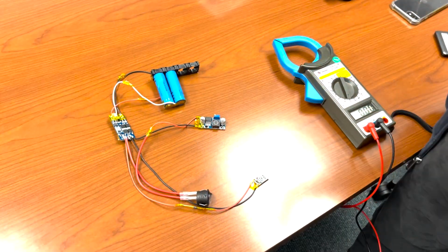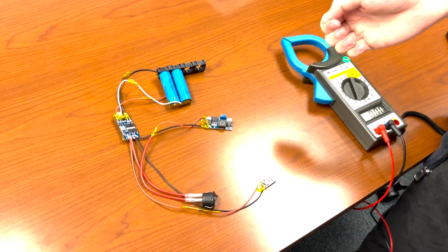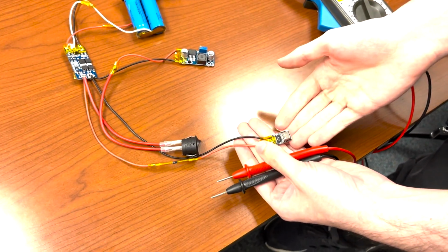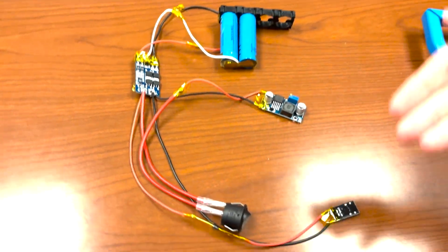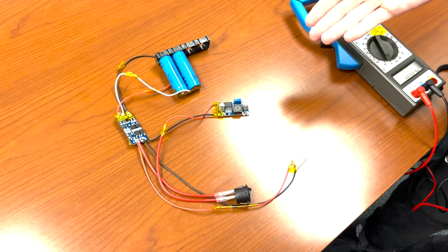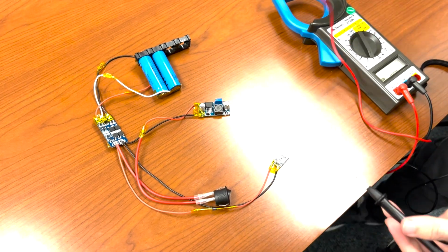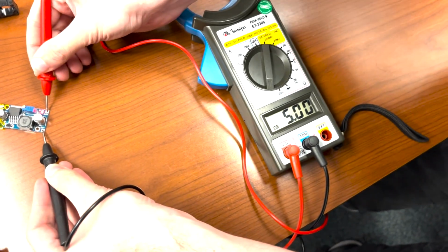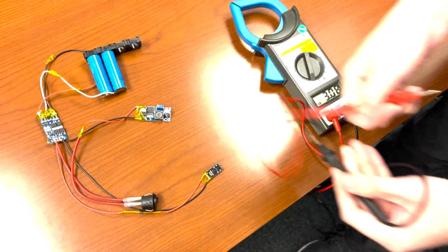Here's a prototype version of our design for the battery system. The system is rechargeable through USB-C design with a 9-volt input that goes to the batteries, and finally to a voltage regulator that will be powering the rest of our systems that we showed earlier. Just to show, we can measure the voltage on the output of the voltage regulators to show that it gives us an average output of 5 volts that we'll be using for our project.